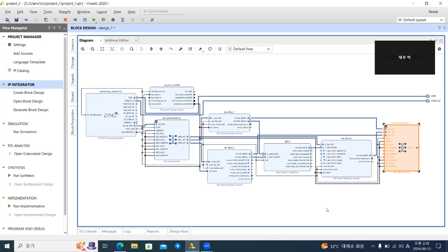That's a fascinating question. Do we need to keep track of the ordering when you connect these wires? Can you mess up with them? That does not matter, because the AXI interconnect is in fact an MMIO device, memory mapped IO. If you're not a computer science major, you think what the hell is an MMIO? But basically an MMIO means that the CPU will talk to these devices at a certain memory location. That's why the wiring here is not important. It is only the memory mapping that is important. And we are actually going to do that.